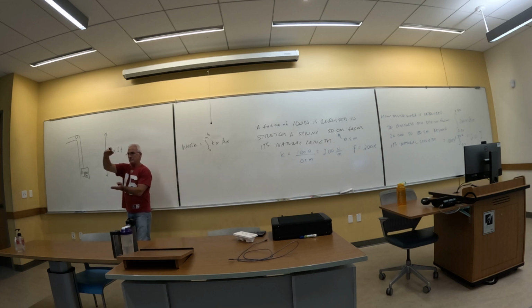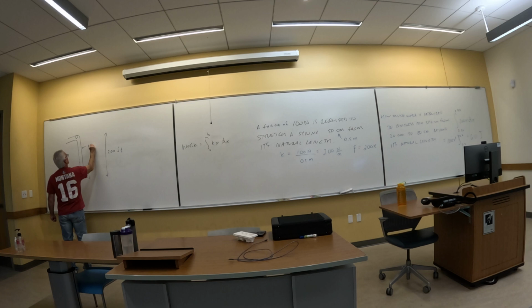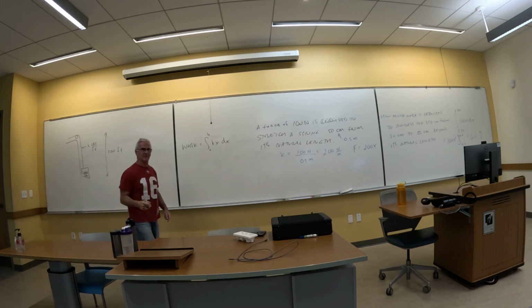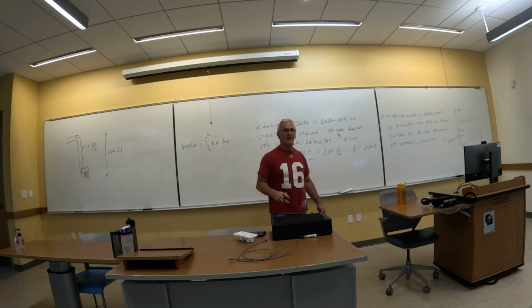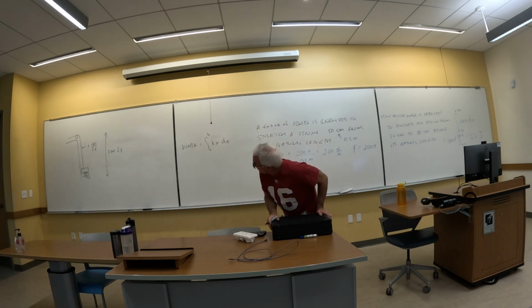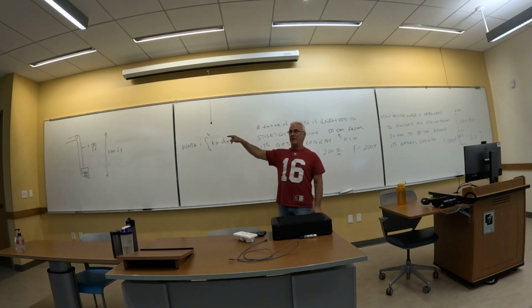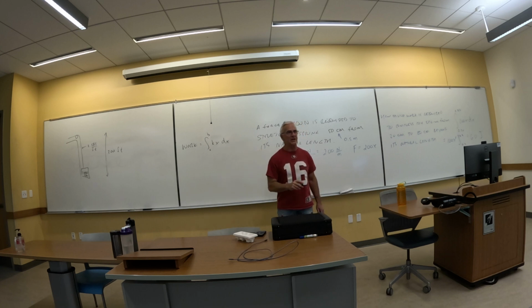Now, the cable, it's a pretty strong cable. So let's say the cable weighs 2 pounds per foot. That would actually be a pretty heavy cable, but I'm going to need something heavy. So I'm going to pull this thing up. Now, can I simply multiply the 1,000 by 200 to find the work done in pulling up just the weight itself? Yeah, because that's not changing. But I have to do something about the cable because the cable is changing.